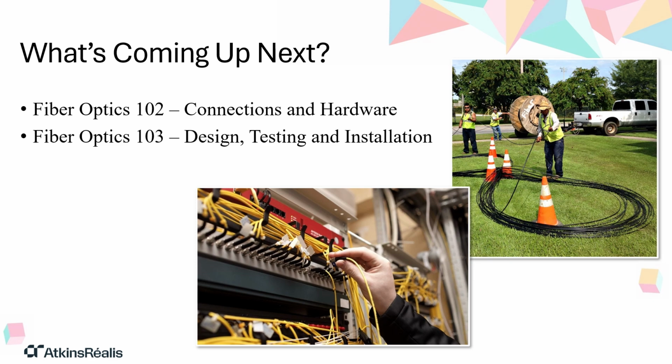And finally, we wanted to learn what fiber optic cabling is used in typical construction projects. So we talked about the components of a fiber, whether that be the individual fiber itself with core, cladding, and coating, or how those individual fibers are rolled up into buffer tubes, and how each cable is constructed of multiple buffer tubes, multiple fibers, and also additional components like the central core member, the outer jacket, and everything in between. We also discussed the various types of fiber optic cables, from loose buffer tube to armored to aerial communications.